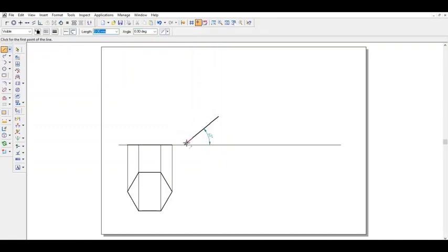Again project, I know this is a corner, so the corner will always be here. I know here these 2 points are this one and this one, so I know this will be along this line. The alignment indicator will help you a lot whenever you are projecting the lines. Similarly you are going to get one more point here, so this corner will be here. So here you are going to have one point and another line here, so this becomes already an edge.